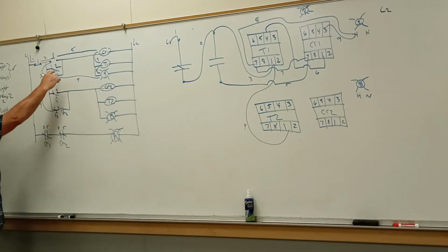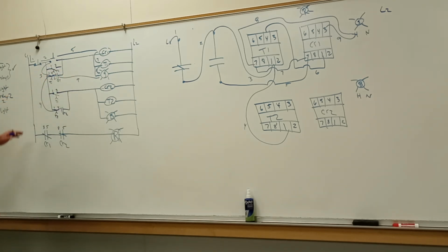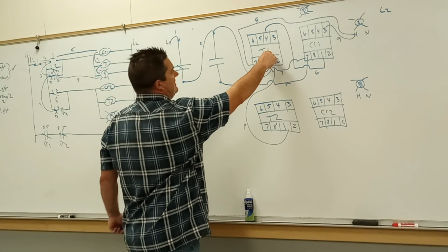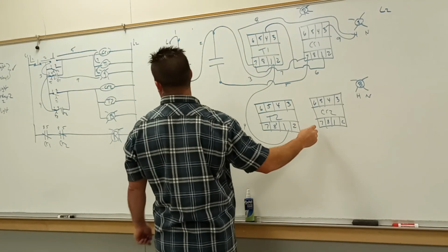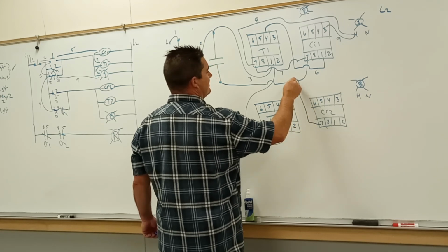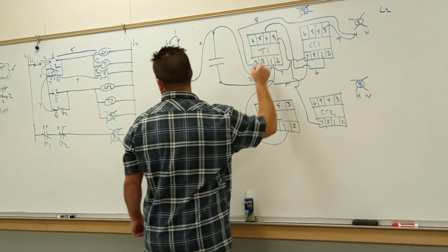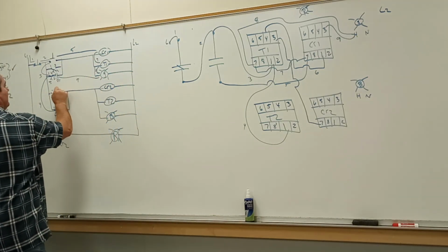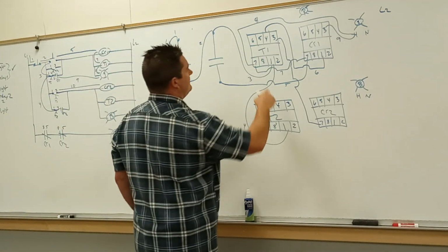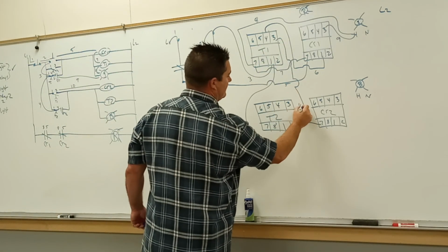I've got everything done except this. I'm going to do it in steps so you can kind of go through that process. So now we've already done T1 number 1. The number 3 fires control relay 2. So T1 terminal 3 fires control relay 2. Oh boy, it's going to start getting messy. And that's wire number 10. It's wire 10.